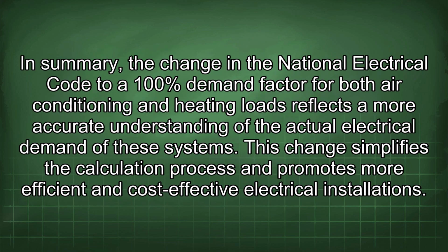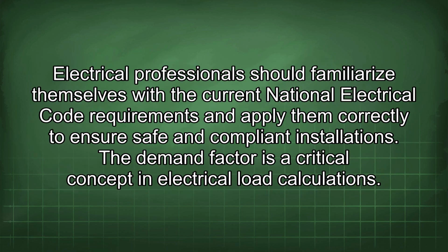In summary, the change in the National Electrical Code to a 100% demand factor for both air conditioning and heating loads reflects a more accurate understanding of the actual electrical demand of these systems. This change simplifies the calculation process and promotes more efficient and cost-effective electrical installations. Electrical professionals should familiarize themselves with the current National Electrical Code requirements and apply them correctly to ensure safe and compliant installations. The demand factor is a critical concept in electrical load calculations.